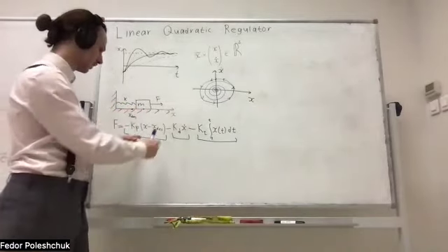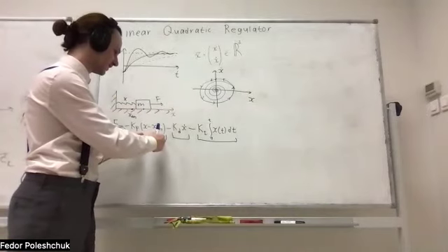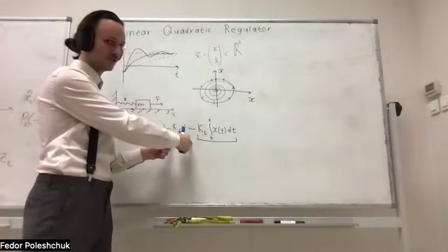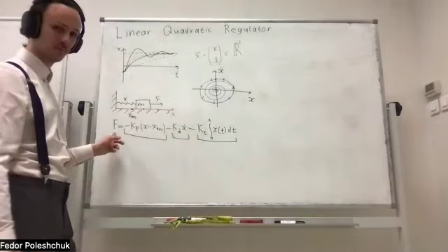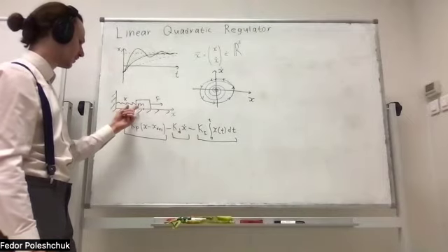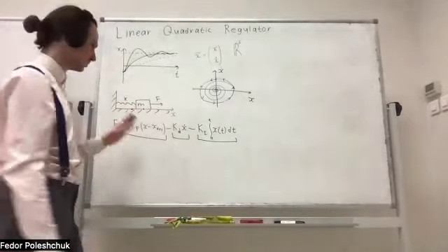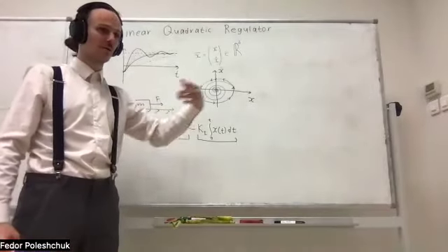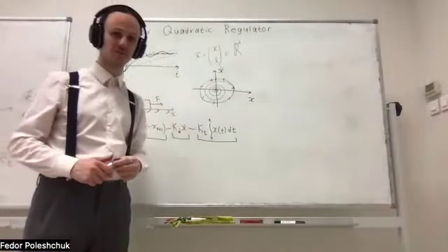What will happen? Well, the deviation from the desired position is zero. This middle term is zero, and the force is zero. So our controller will not act upon this block, and it will start accelerating far away from the desired position.